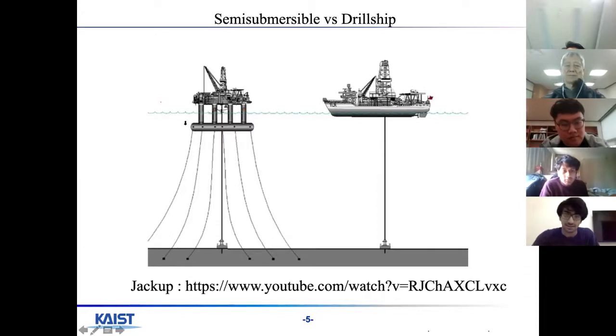It's semi-submerged inside the sea. And this is the drill which is used. And as you can see, these wires are basically to provide more stability. A semi-submersible platform, as compared to the drill ship, has good ship stability and is also better at sea keeping than the drill ships. And for jackups, I have this video which I'll show you.